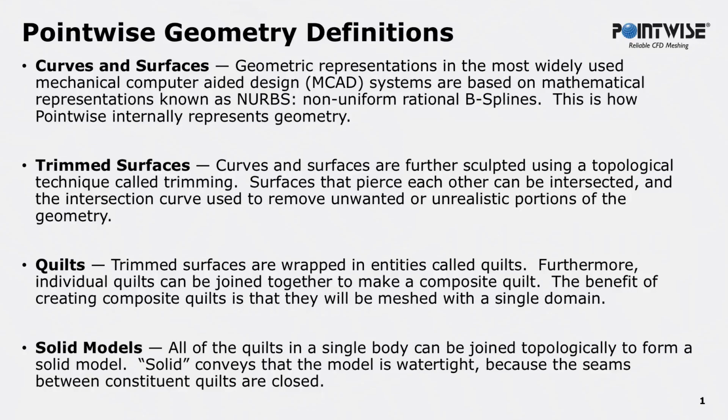It has to be in order to resolve the very small spacing usually associated with boundary layer resolved grids, which are typically orders of magnitude smaller than the tolerance used by the CAD tool in creating the geometry. When a model is imported, the additional precision of Pointwise may expose flaws in the underlying CAD surfaces and their topological association, which don't appear in the CAD tool itself.